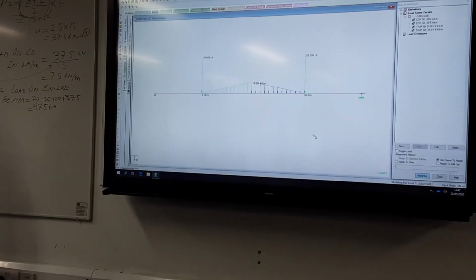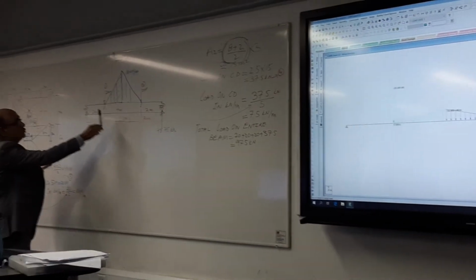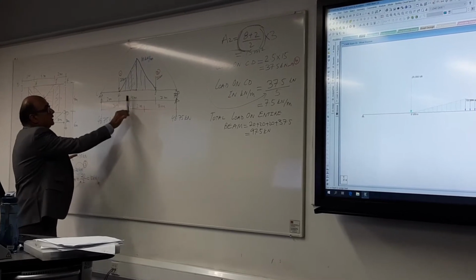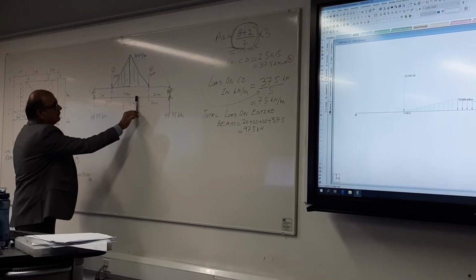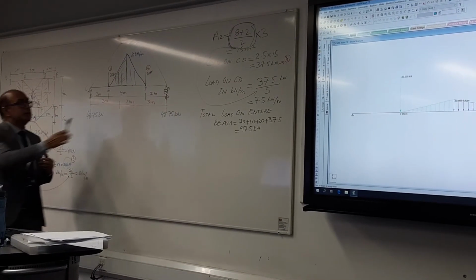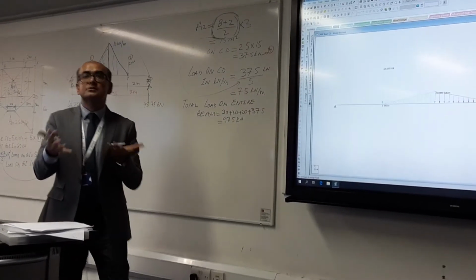So add it, and then simply click on that, and then click on assign, and then the triangular middle load is assigned now. Now, I will define this trapezoidal load in parts. One is from 0 to 3, which is triangle. Another is from this 3 to 5, which is kind of a rectangle, and then from 5 to 8, which is again a triangle.